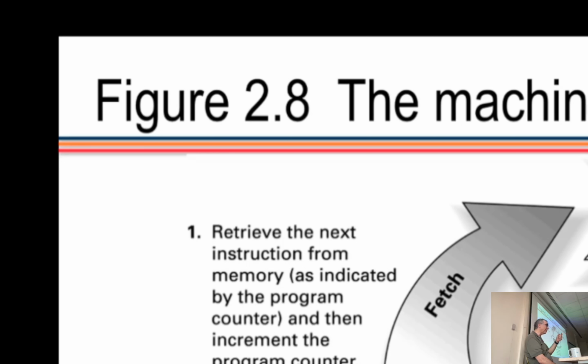If the program counter shows 5, it goes to the 5th location and gets the instruction. If the program counter shows 20, it goes to 20 and gets the instruction. And at each cycle, it is automatically incremented by 1, or sometimes 2: 20, 21, 22, 23. So that is the next line in the program. In this architecture, it goes 2 by 2, because our instructions are 16-bit and location addresses are 8-bit.